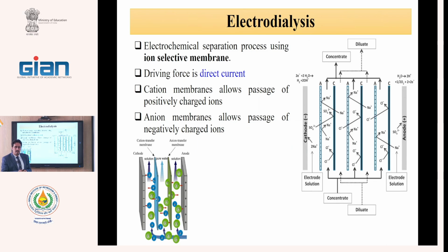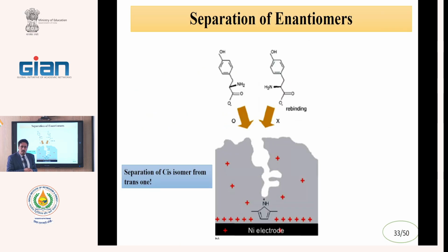Previously you mentioned isomer separation with respect to pervaporation, where a boiling point difference is required. In pervaporation, we need a difference in boiling point between two isomers. But here it's not needed. Separation is based on structure.